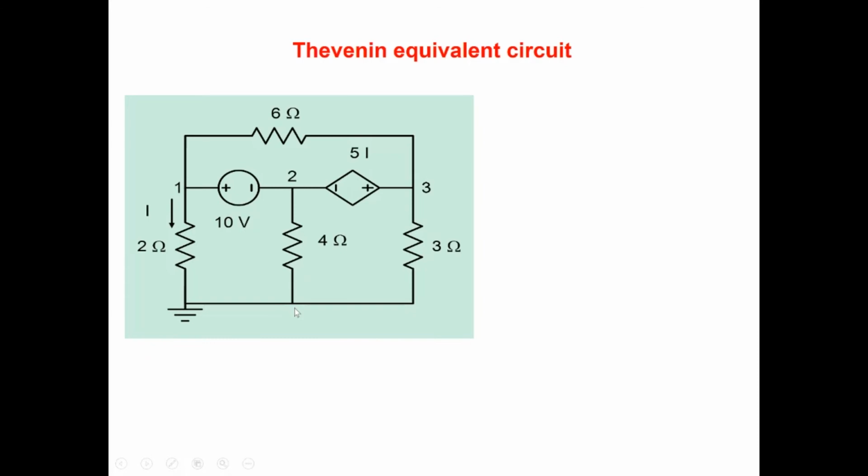Note that when we build Thevenin's equivalent, we'll get the voltage across node 2, but we will not get the voltage at, let's say, node 3, because Thevenin's equivalent takes the rest of the circuit and transforms it into a simplified circuit, which gives us the real value of the voltage at 2, but doesn't give us anything else.